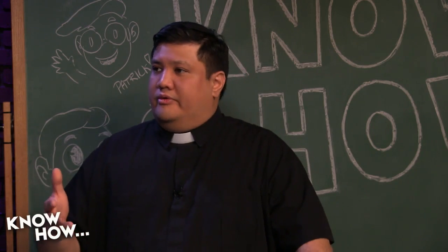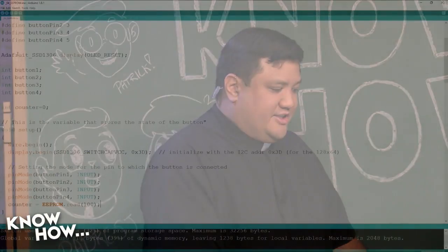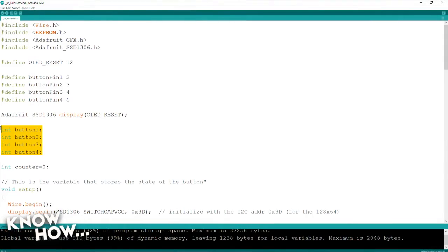But then can you store those values that you need, I guess, just in the flash memory then? You can. Yeah. But you're going to lose them. Well, yeah, precisely. So, for example, if you go back to my screen, up at the top, I have those right here. So all of the variables I declare, that's all going to be in the system memory. I can't write to that flash memory because that flash memory is what my program is. Ah, that would be bad. Right. We would not want that. That would cause really bad things.